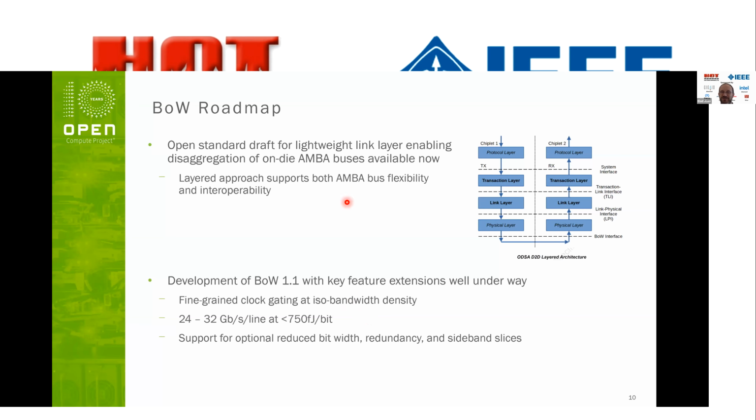Now, what's really important here is that from a latency perspective, these are things that really need to be in the single-digit nanoseconds. And so one really has to build the link layer, and how it interoperates with the PHY, in a very specific and targeted way to ensure that you can keep those latencies to an absolute minimum, because you're starting from the on-chip world. So that's something that people are very, very sensitive to. So there's a layered approach that was taken here.